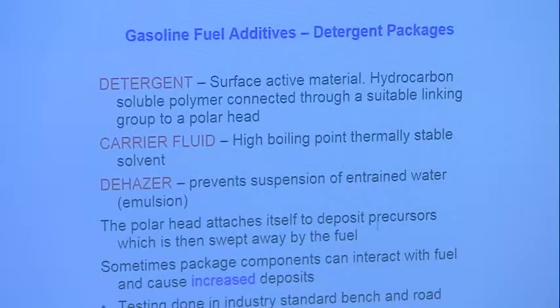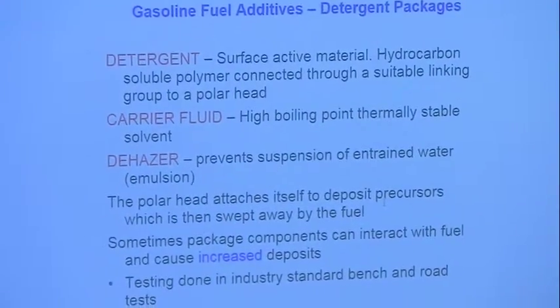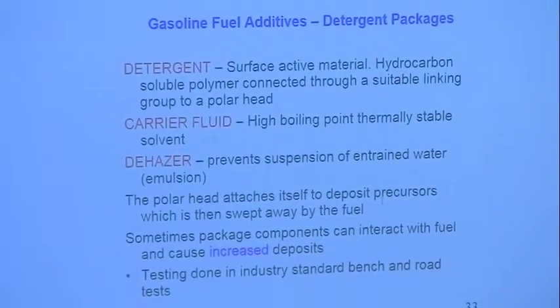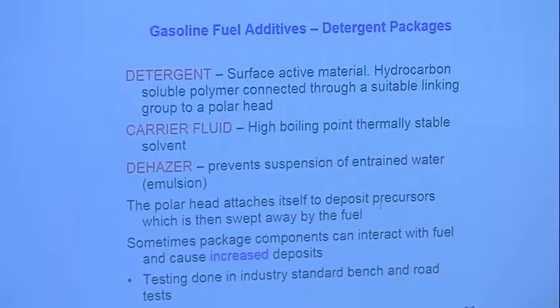And in terms of detergent packages, what are detergents? They are surface active materials, essentially a hydrocarbon soluble polymer connected through a suitable linking group to a polar head. The polar head is the important thing here. And they have carrier fluids, a high boiling point, thermally stable solvent, and a dehazer. This is what a multifunctional detergent package might contain.